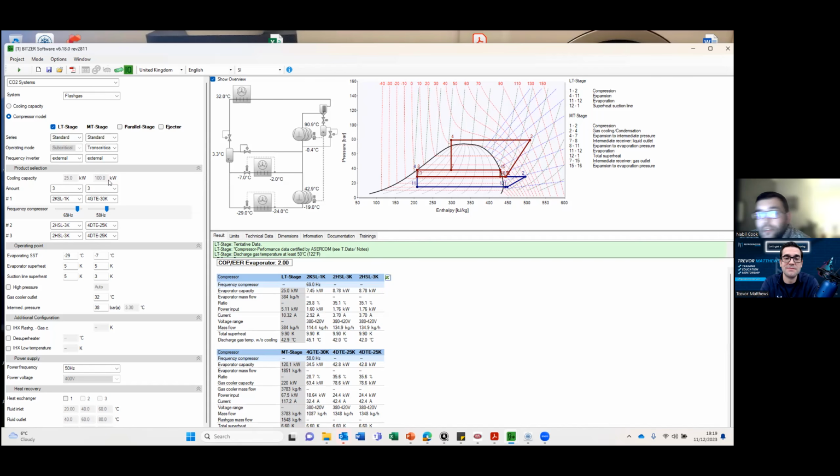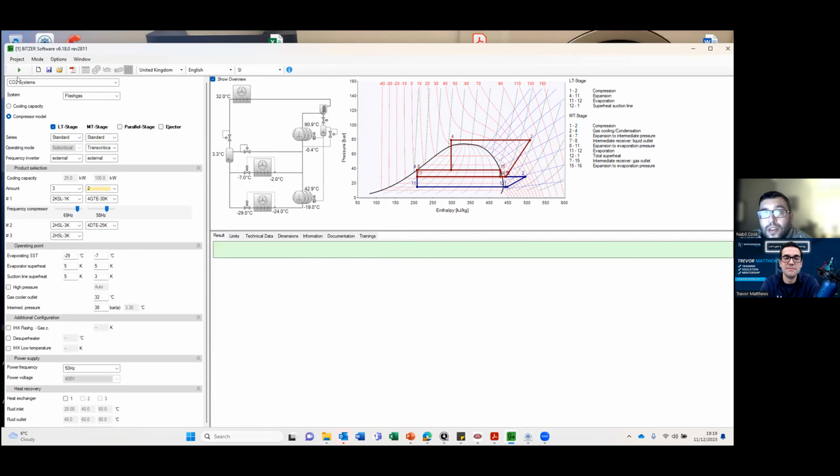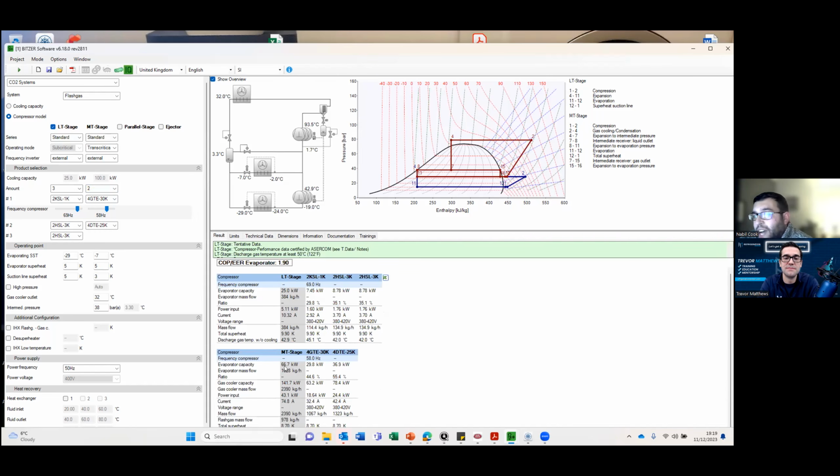Well, what happens if we remove one of the compressors? Oh, wow. We've now shot far under our desired 100 kilowatt. We're at 66.7. And this is why we want to add an inverter, because we don't want the system to be cycling between 66.7 kilowatt and the 120.1 kilowatt, just on the desire to somehow hit some sort of waveform mean of 100 kilowatt in between.